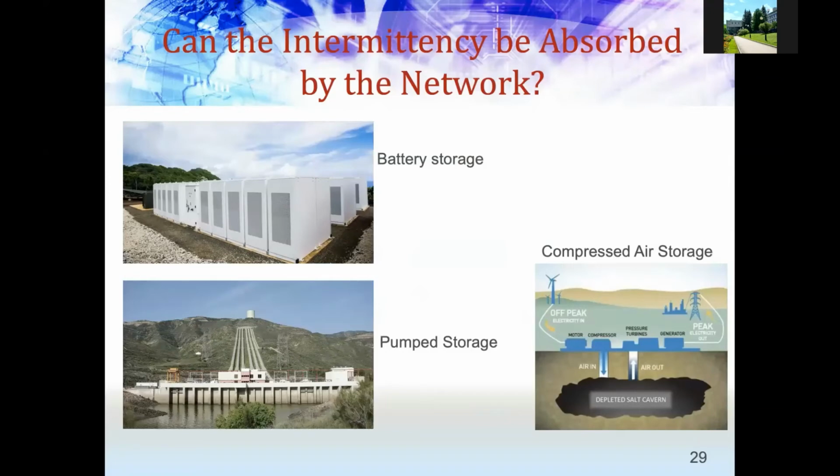We have battery, which we talked about. We have pump storage energy. We have compressed air energy storage as well. Battery we all know very well, fine. Battery is expensive. It is typically used for shorter-term variations. Pump storage, on the other hand, can be used over a weekly cycle. You fill it over the weekend, use it during daytime, fill some more at night, use the stored water the next day. It goes on for a long time, but you cannot put a pump storage plant everywhere. Battery you can, pump storage you cannot.